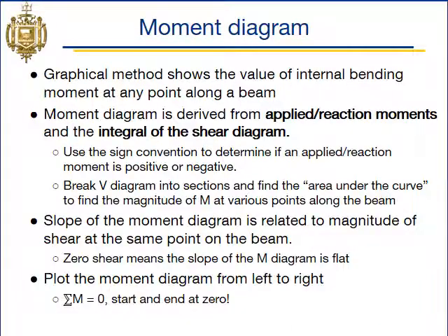All right, so now that we're experts on shear diagrams, let's get into doing the moment diagram. The moment diagram is essentially like doing the shear diagram, except instead of using the vertical forces, you're going to look at applied reaction moments, and then we're going to look at the shear diagram. The area under the curve of the shear diagram and applied moments are going to allow us to plot our moment diagram. The moment can be a little tricky, so make sure you know what your sign convention is, so that you know if an applied moment is positive or negative.